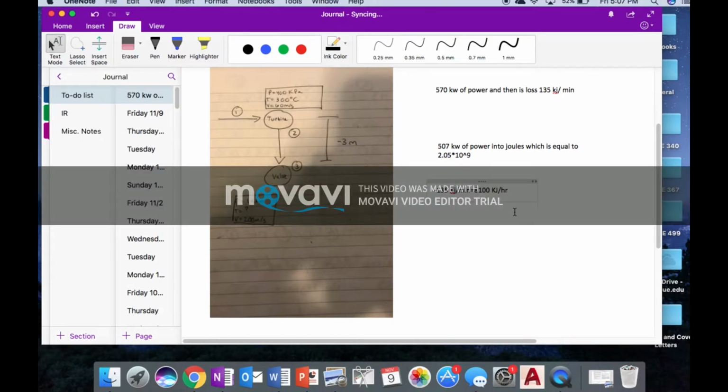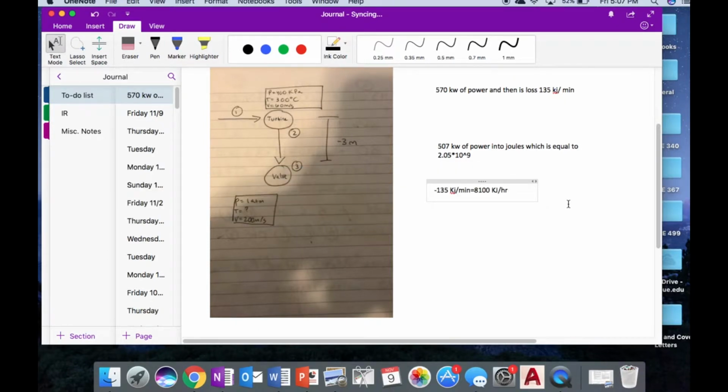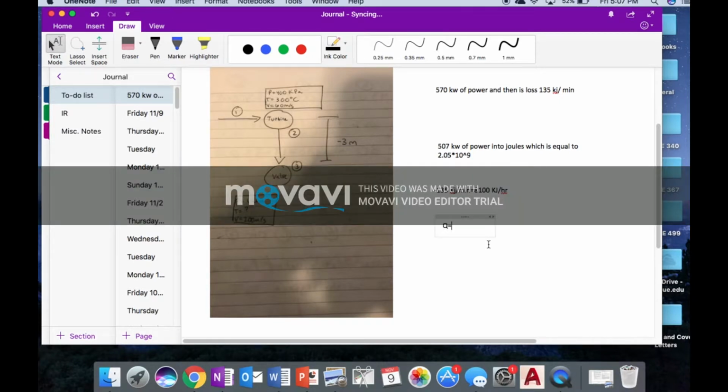So taking that value, I can now do some conversions. The overall goal is to calculate the temperature, the quality of vapor, and so on. So before I do that, I want to go after the enthalpy. And to calculate enthalpy, for the first couple values in enthalpy, I'm going to calculate Q, which right here is equal to the heat loss divided by that flow rate, I guess, of how much water vapor is taken in.